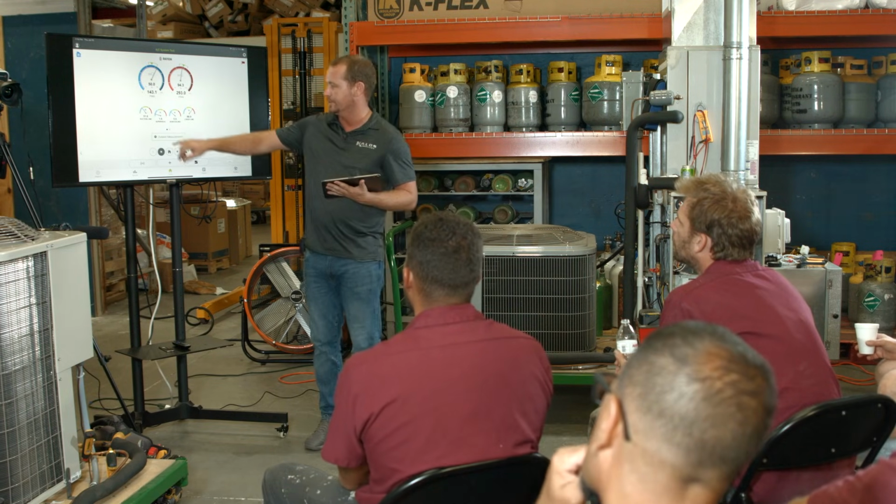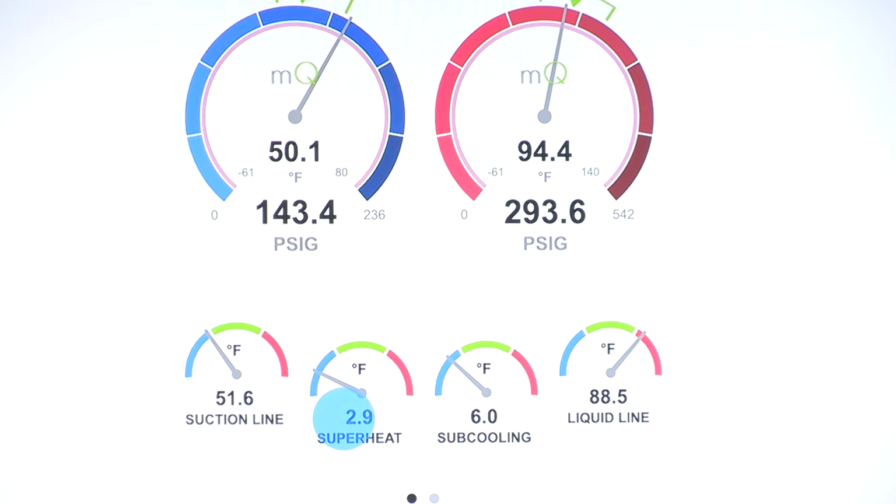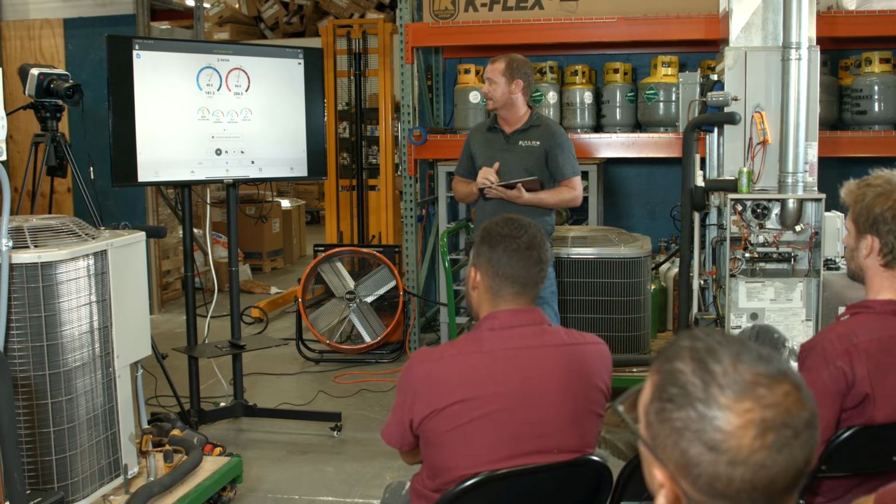Let's focus here. Our suction line temperature is too low, just above 50 degrees. So we have a problem. We can click on it to see full information about that problem. Our superheat is hunting a little bit.